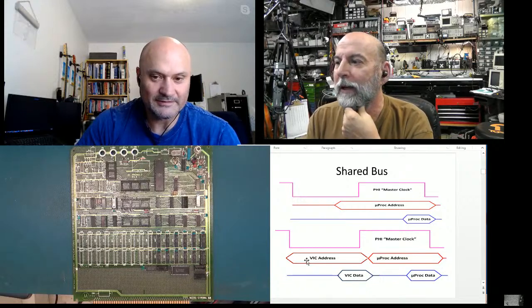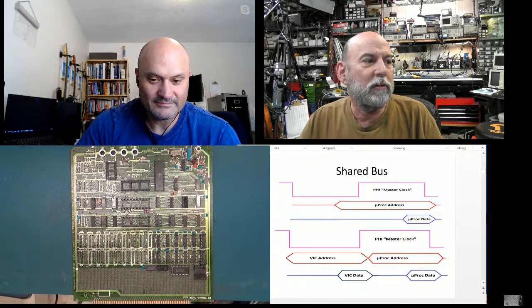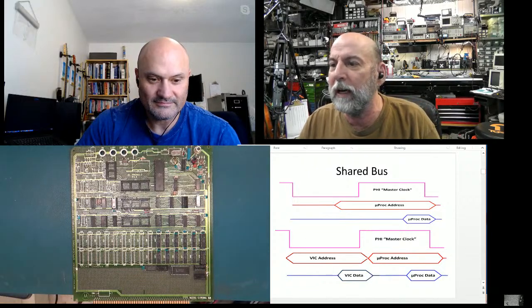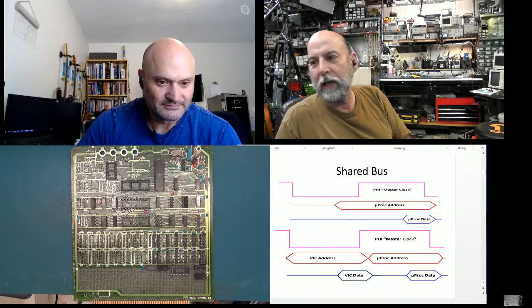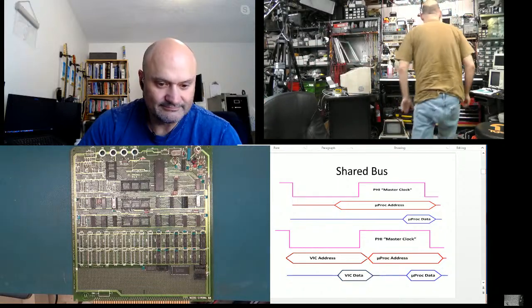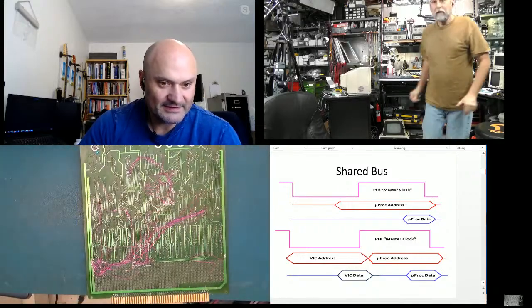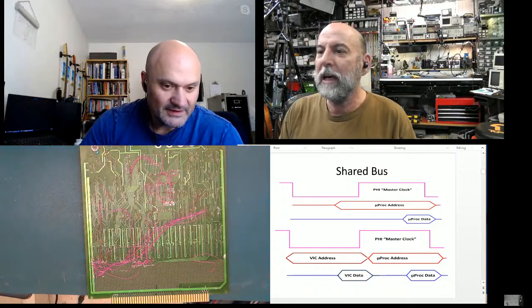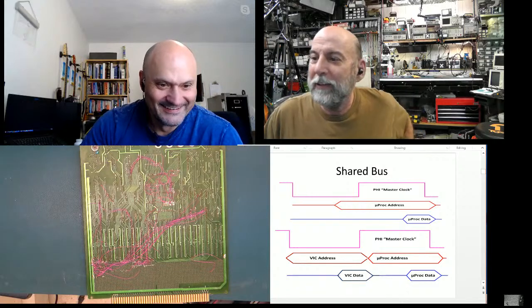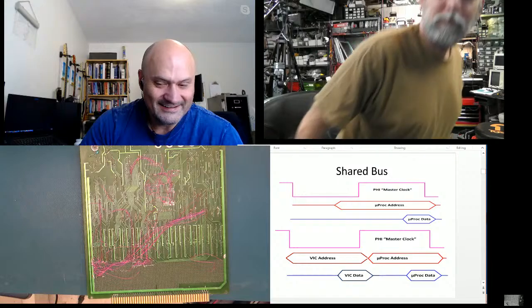Right on. So here's this technique. It turns out I had done this at home using this board you see here in the bottom left. Matter of fact, this started as a Motorola board. I converted it to a 6502, and then I wired the heck out of it to make it split bus. This is actually using 2114 static RAMs. It's a surprisingly small amount of wires, but it was a big amount of wires to do at home on your desk. That's incredible.